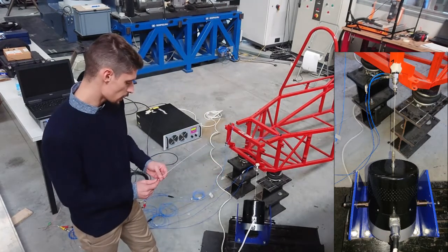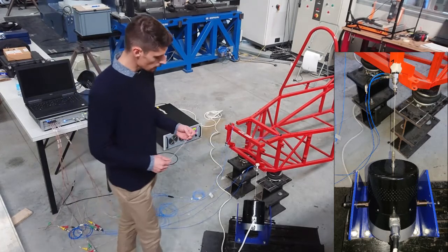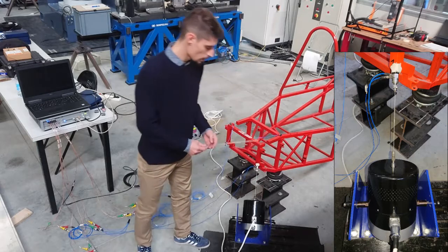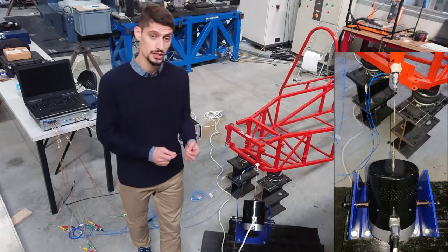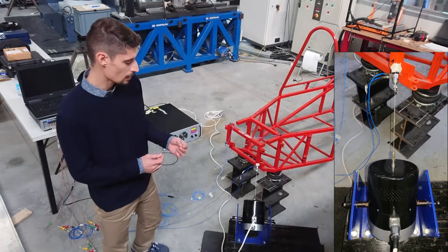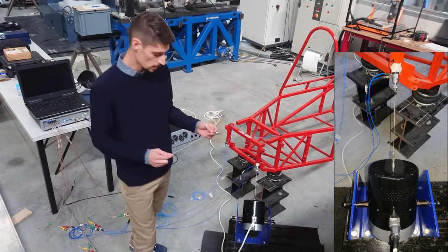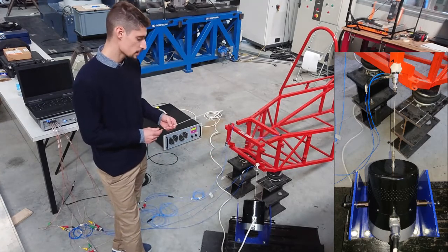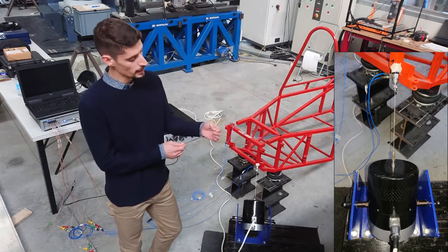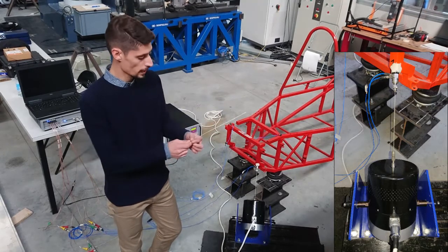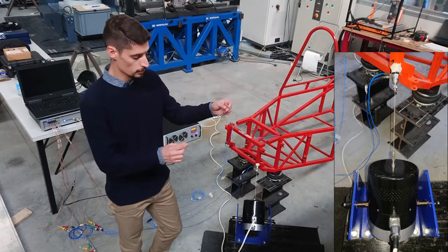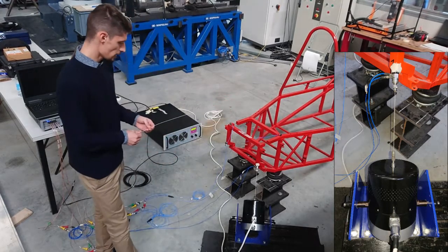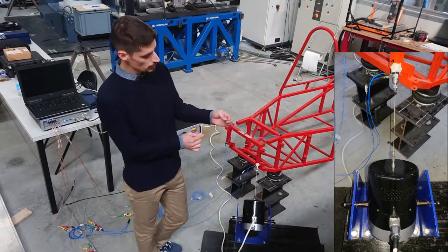So basically the role of the stinger is to decouple the shaker from the structure and to apply just the axial force, avoiding any side load. So therefore the stinger is designed to be rigid along the axial direction, and flexible along the lateral direction. Okay, the length of the stinger is important too,